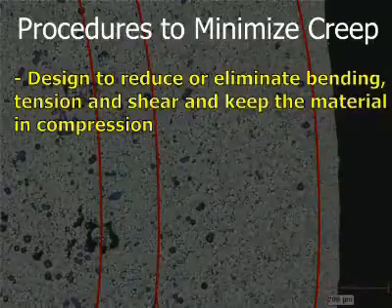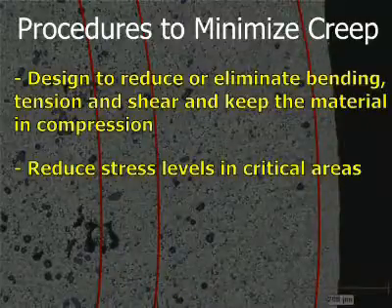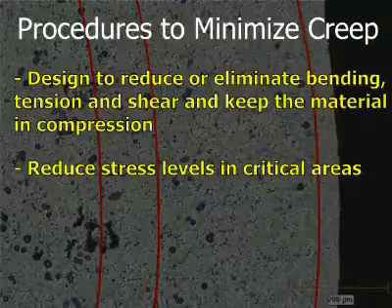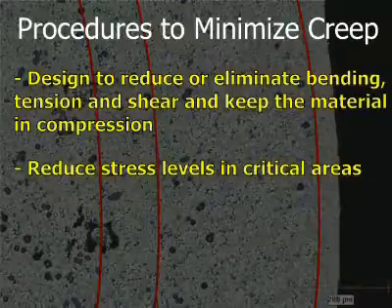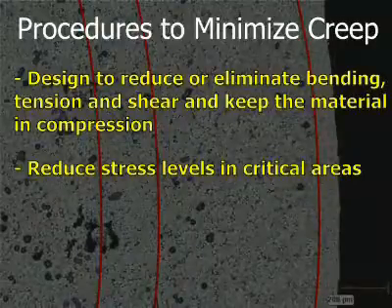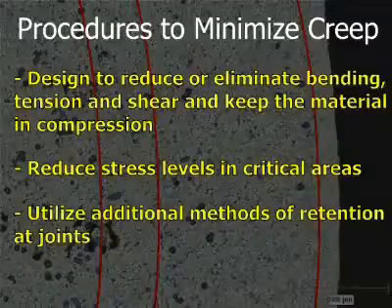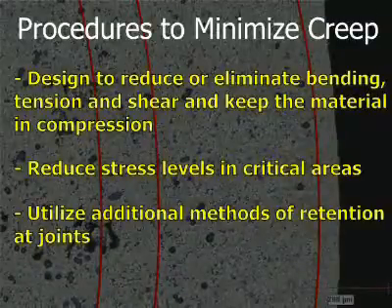Reduce stress levels in critical areas. For example, washers under nuts and bolt heads and increased depth and diameter of threads increase the area of load carrying metal. Utilize additional methods of retention at joints, such as bolting or staking, where members are retained by press fits.